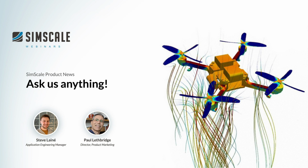Thanks. All right. Thank you, Steve. Excellent. All right, let's have a look. Okay. Does the vibrational simulation provide a mass participation plot? Yes, there are various plots that you can get out of the post-processor, and when we're calculating the eigenfrequencies, we're taking the centrifugal forces into account and also the gyroscopic effects. And you can get the full detailed table out of the post-processor.